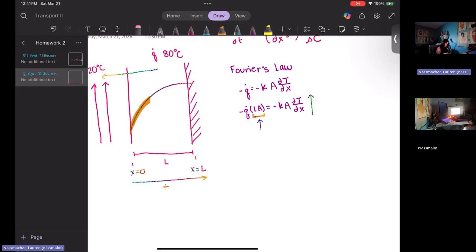And as it levels out, our length multiplied by our cross-sectional area becomes smaller, so our slope becomes smaller. And the reason that those three values are changing is because the thermal conductivity and cross-sectional area do not change, as well as the heat flow. The heat flow remains constant within the slab.